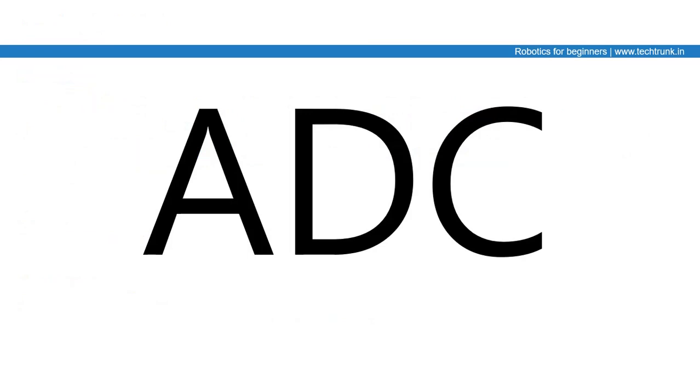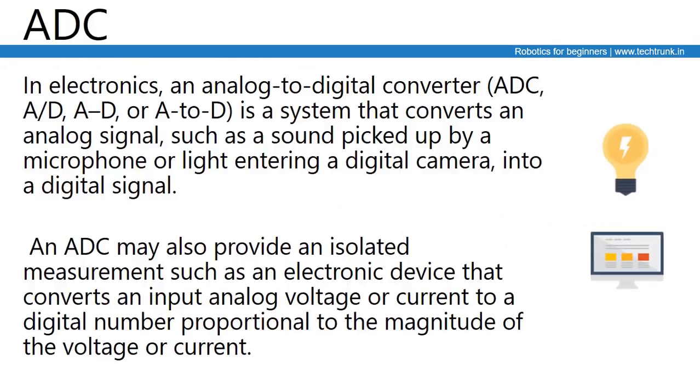Now we'll talk about ADCs. In electronics, an analog to digital converter, or ADC, A to D converter, is a system that converts an analog signal, such as sound picked up by a microphone or light entering a digital camera, into a digital signal. An ADC may also provide an isolated measurement, such as an electronic device that converts an input analog voltage or current to a digital number proportional to the magnitude of the voltage or current. Let us say the ADC is of 10-bit precision, then it will convert 0 to 5 volt values to 0 to 1023 digital values.